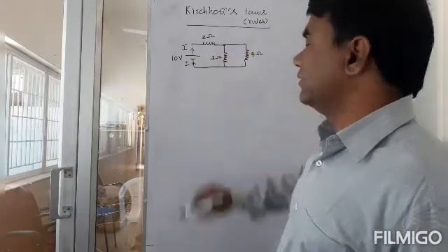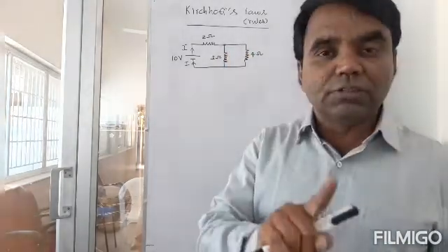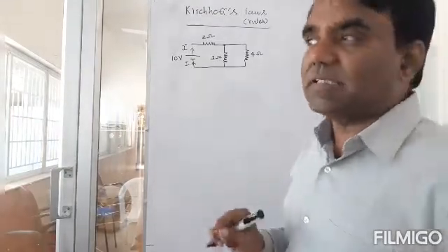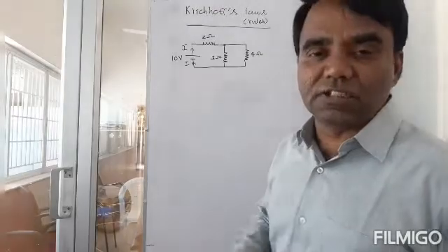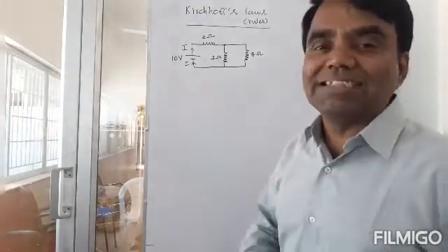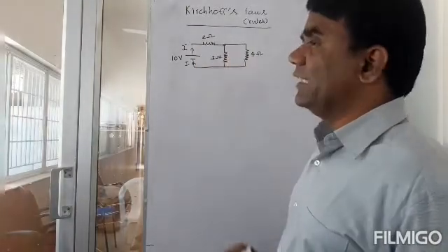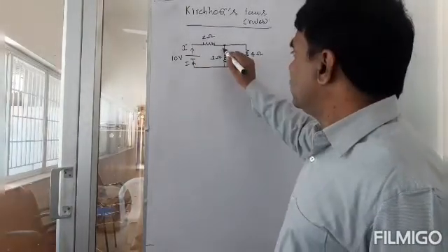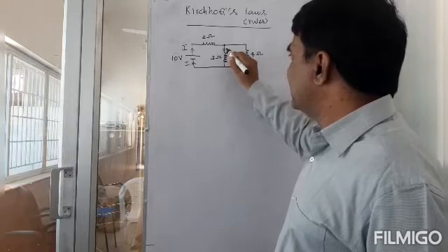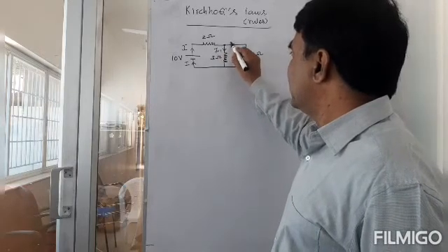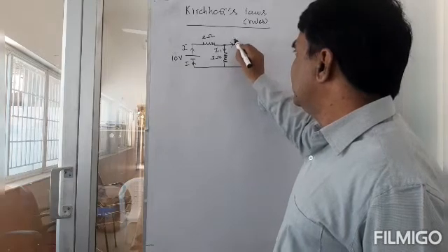You find a junction here. So now can I use the first law, the junction law? What does it say? It says that the amount of current entering the junction must be equal to the amount of current leaving the junction, right? So I is the amount of current entering the junction. And I don't know what current is going to leave the junction, so I'll say it's I1, and I'll also say this is I2.